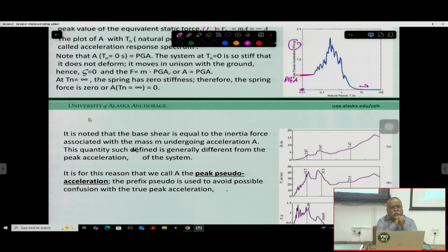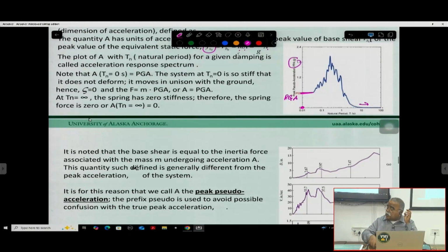So what you do is actually, as I can show you, this is your time period, the time period of the building, right? But the building period you may or may not know. But whatever the ground motion is, you calculate this response spectrum, and then if you know your building values, or the omega n values, then you can calculate for that earthquake what acceleration spectrum is expected, right? So you can do it in a reverse way.